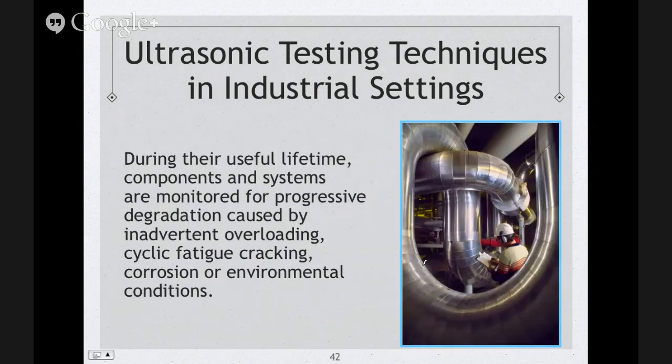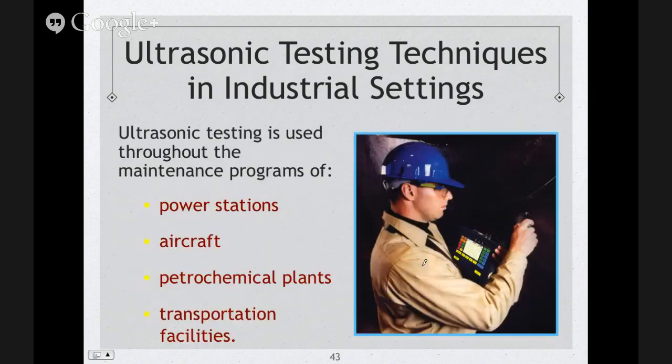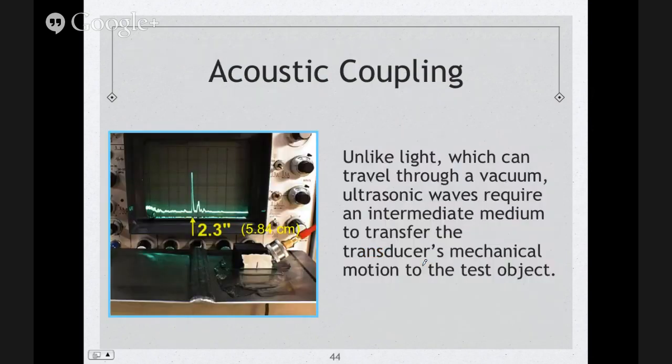During their useful lifetime, components and systems are monitored for progressive degradation caused by inadvertent overloading, cyclic fatigue, cracking, corrosion, or environmental conditions. Ultrasonic testing is used throughout the maintenance programs of power stations, aircraft, petrochemical plants, transportation facilities, and others.